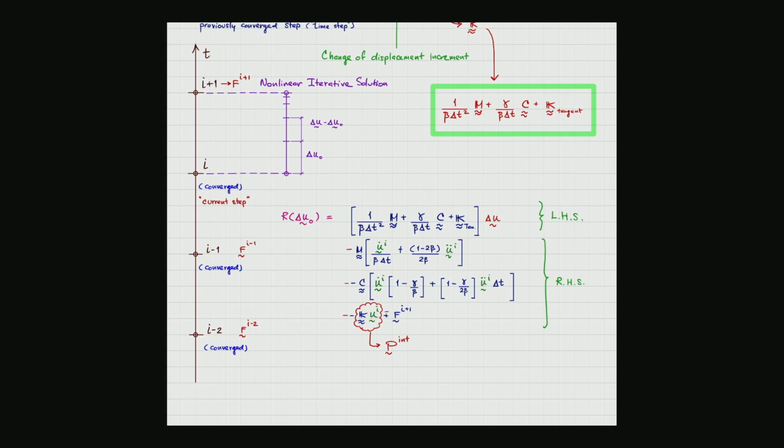Likewise, not only just the spatial domain, we are talking about the time domain now. And in the time domain, the implicit time integration is like the Q elements, a very nice, novel scheme, very useful when the time stepping size is allowed to be bigger, when you are dealing with a problem where the nonlinearity is not so crucial, it might be your choice. It might be good for the time that you do not have the nonlinearity.